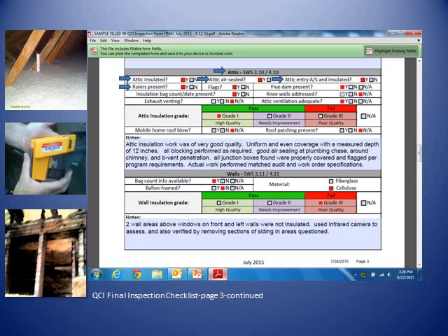Next question. Are there depth rulers present in various areas of the attic to indicate uniform depth of the attic insulation that was installed? Are there flags installed to mark the location of any junction boxes? Indeed, there are. Are flue dams present to isolate and prevent flues or other heat-producing devices from touching blown insulation? Yes, they are present.